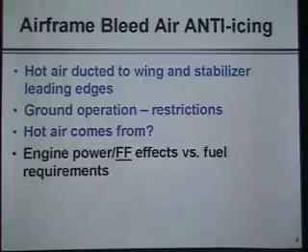Whether it's forecast icing or known icing, in either case, you're expected to be in the icing conditions, and you are expecting to have to run your airframe bleed air, and of course if you had an engine bleed air, you're going to have to run your anti-icing systems. And if that affects your fuel flow, you've got to put that fuel on board the airplane prior to takeoff, whether it's Part 91 or whether it's Part 121.